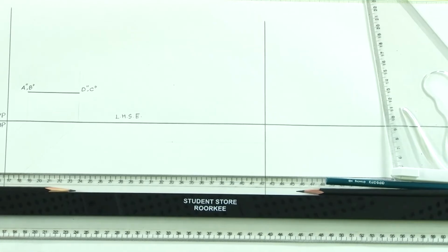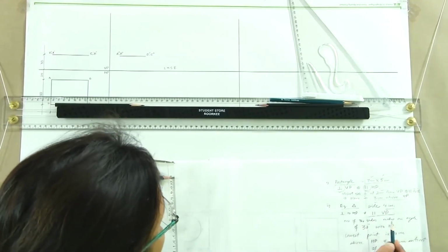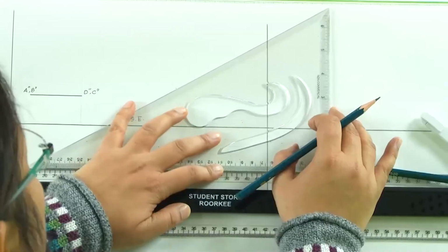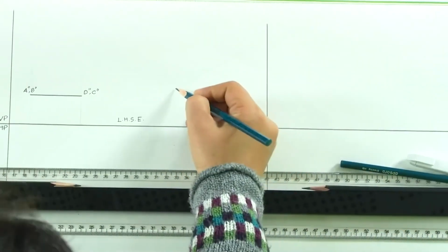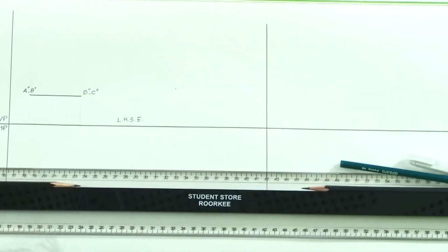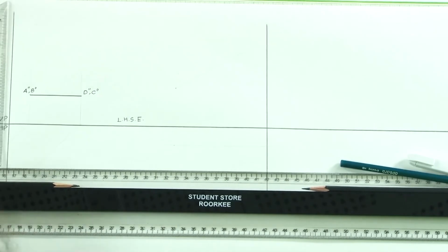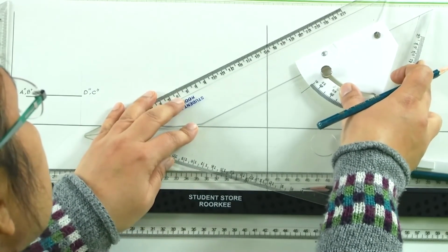Now, this is an equilateral triangle, and what we have is the side of this as 4 centimeters and one of the sides makes an angle of 30 degrees with HP. So, suppose we draw this line starting from this point, which is fulfilling these two conditions at an angle of 30 degrees. Now, this triangle has a side of 4 centimeters. So, we mark 4 centimeters here.